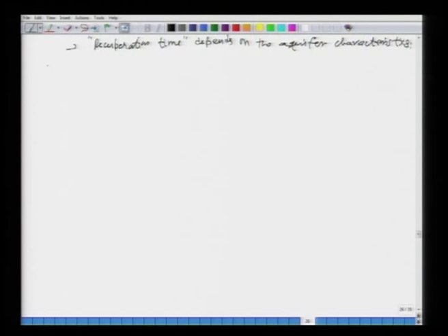The next thing, the last point I would like to make about all this process of pumping, formation of the cone of depression, recovery, all of this: what happens in the case of a confined aquifer? We talked about all those things for an unconfined aquifer. Let us say you are pumping deep into a confined aquifer. Same thing happens there also. The confined aquifer also undergoes similar changes.